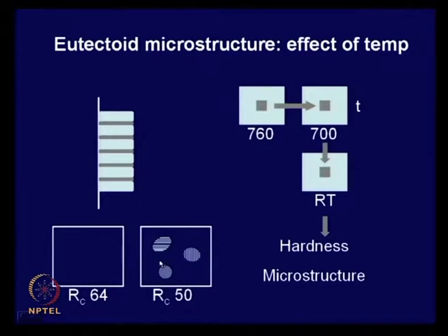And as the amount of this pearlite increases, you will find that the hardness decreases. Here it is RC 50. You keep it for a little longer time, you will have more such nodules, and you will find its hardness is still less. And this type of experiment, if one does,